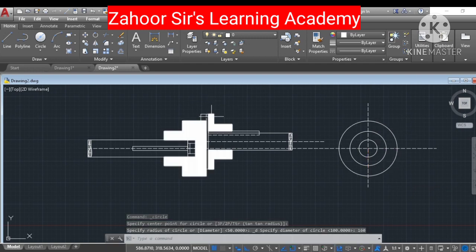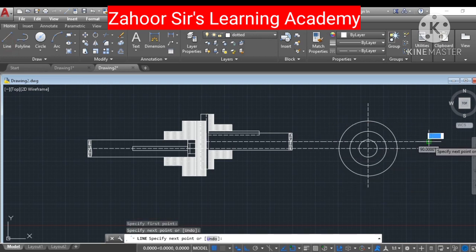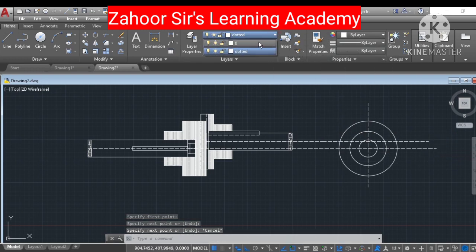One more thing which we will see from that end is this circle, but the center of that circle is different. So we need to extend this line. For that I will take you to the layer. I will change the line to the dotted one and extend this line up to this point. This is how we have to do. Then I can go back and change it to continuous again. Now this is my center for that circle.